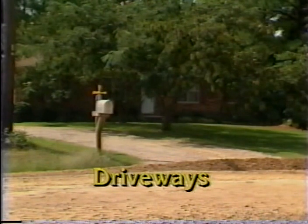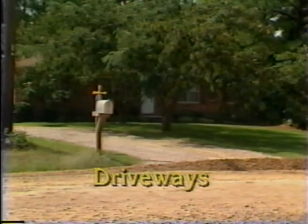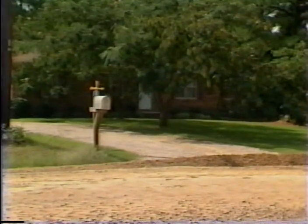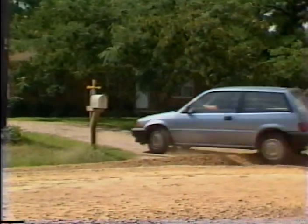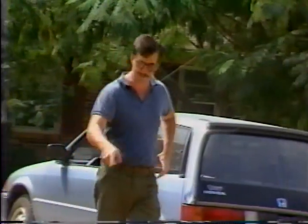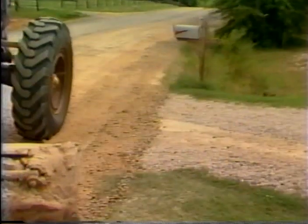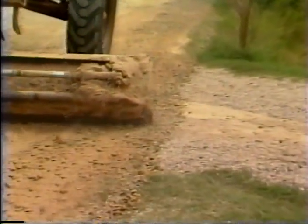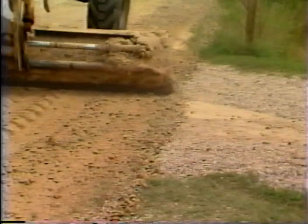The next special condition is driveways. Although governmental agencies are not in the business of maintaining driveways, a smooth transition is desired for driveways onto the road surface. It is not good public relations to leave a large bump or big drop-off at the end of a driveway along the roadway. Allow for smooth transition at driveways when performing maintenance on gravel roads.